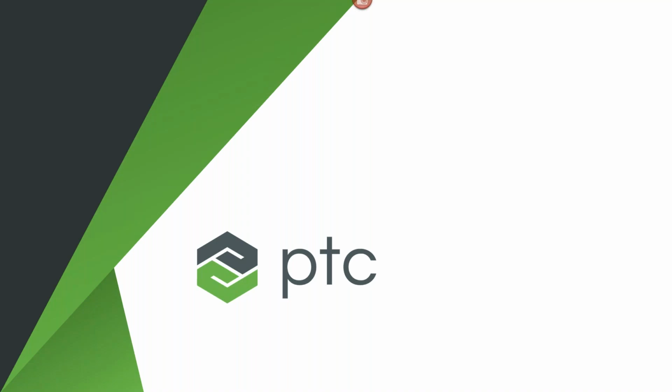All right. Hey, thanks for submitting that question. This is Nelson with PTC. A common question we get is, can Creo Simulation Live handle assemblies as well? And the answer is yes, with some caveats, since this is linear only in the first release for structure, thermal, and modal. There are no contact regions with nonlinear capabilities. So assemblies are treated like bonded connections. We do have some examples that fit really well, but the short answer is yes, it does work on assemblies with some caveats.